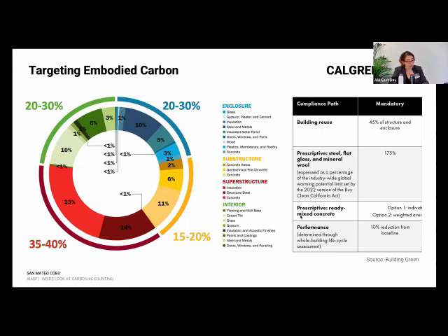There was a plan. I wanted to share with you some of this work here about where is the carbon, right? It's not everywhere. It's not going to be in your door handles. Though we had 1,000 doors on the project, it wasn't there. That wasn't going to move the needle. We focused where the biggest buckets were. So making sure you lean in where the opportunity is. Right now, your superstructure and your substructure is carrying a significant percentage, 50 to 60% of your carbon. And so really working closely with your engineers on that particular scope.